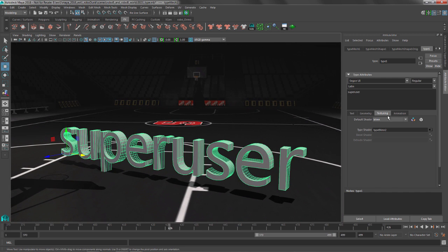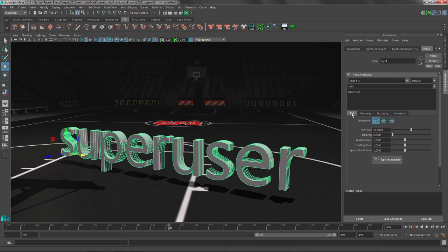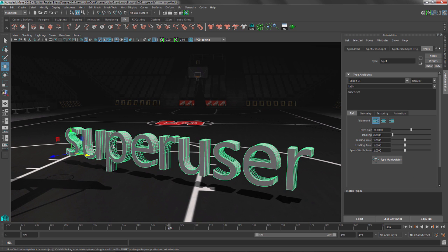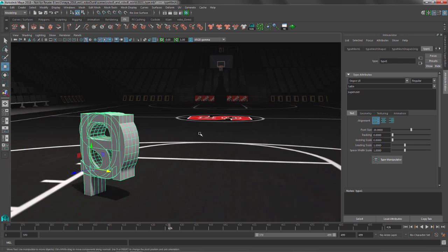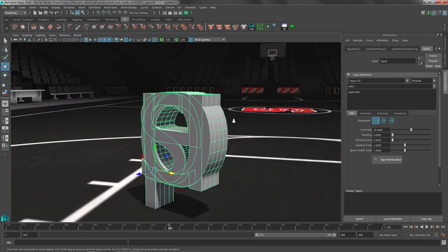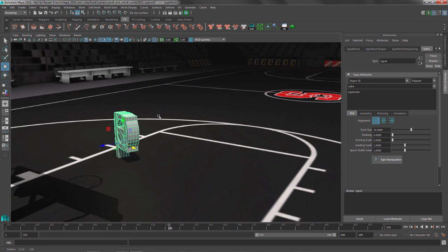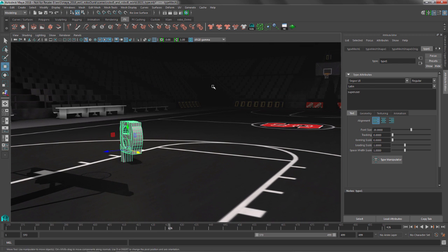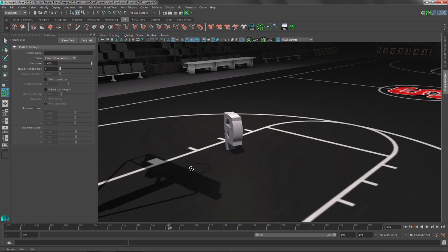And what we're going to do is animate this, but instead of setting keyframes on the animation system, we're going to have an external source drive that. So we want to zero out the pivot, or all the objects, down to the origin. If we just drop that kerning scale down to 0, everybody's basically sitting at the origin. And I'm going to end up driving these with an nParticle system. So let's grab our sketch particle tool, and I'll just start dropping down a few particle points.